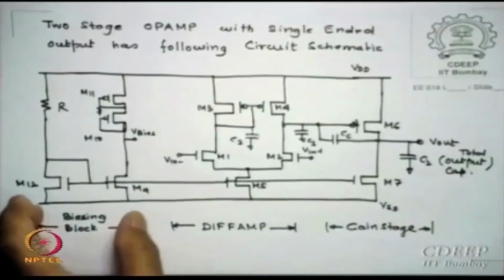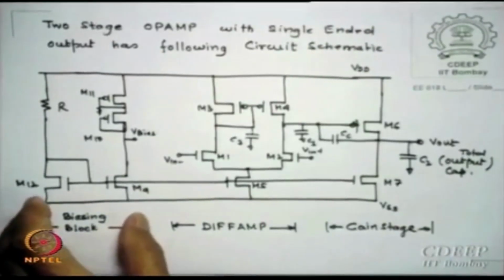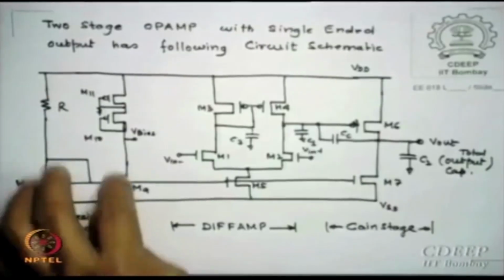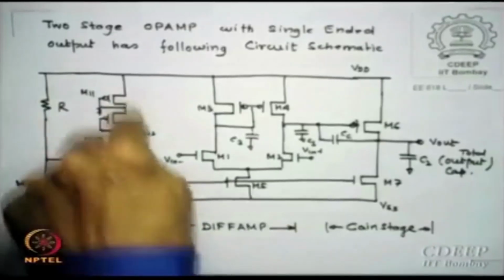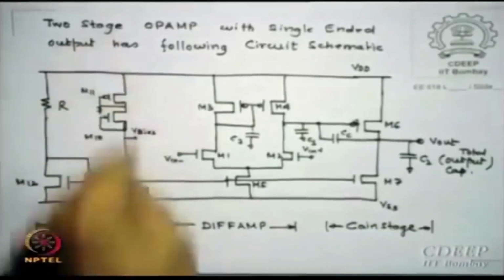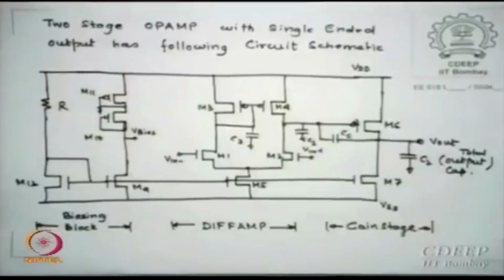So this basic mirror is not really great, but normally same size, and the voltage is created out of the diode drops. To get this drop, you need current. You know this current is this, so you can figure out what the drops are. VDD minus that is your VB. So for example, tomorrow you want to bias this as a current source M3, M4, you can create a V bias of your choice and actually connect there. Is that clear to you?